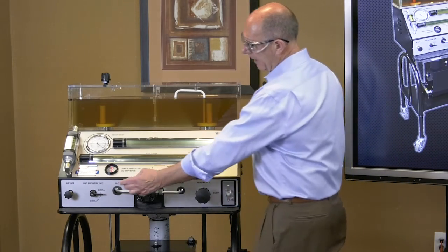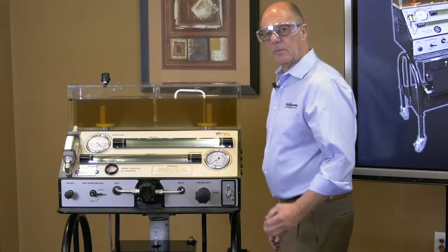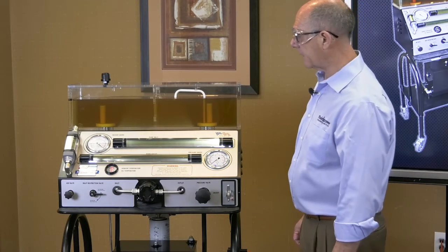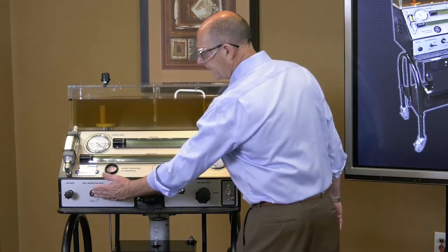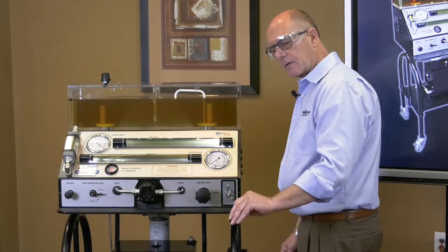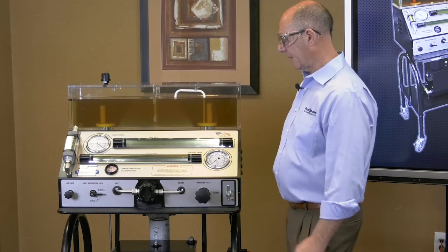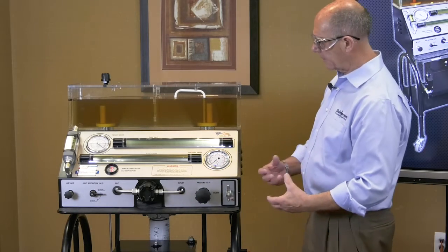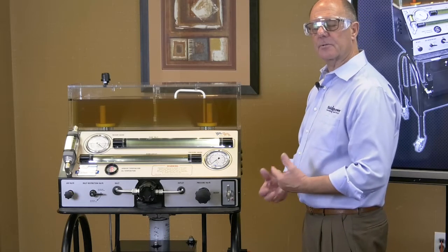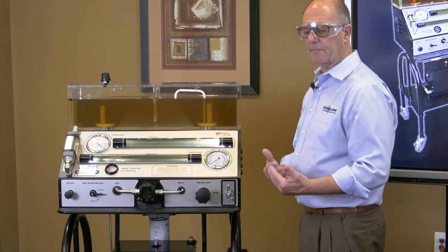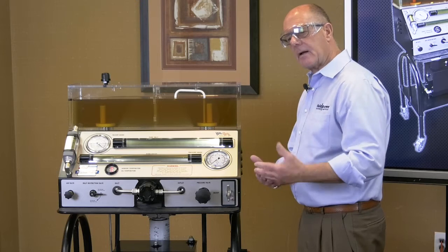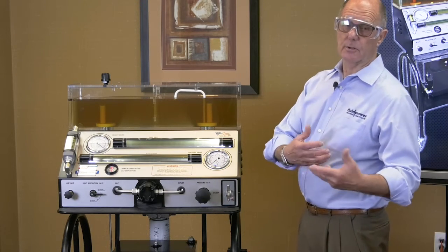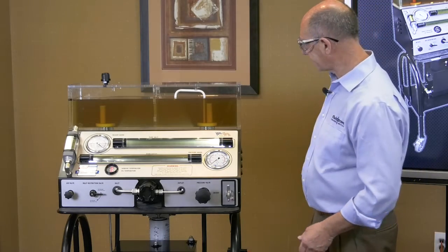Along the bottom here we have a valve that will allow me to let air go into the intake of the pump. Next, I have a valve that will allow me to restrict the flow going into the pump. And this handle here is for a needle valve, which will allow me to create resistance to flow so that we can understand how the pressure relates to, of course, the noise of cavitation.